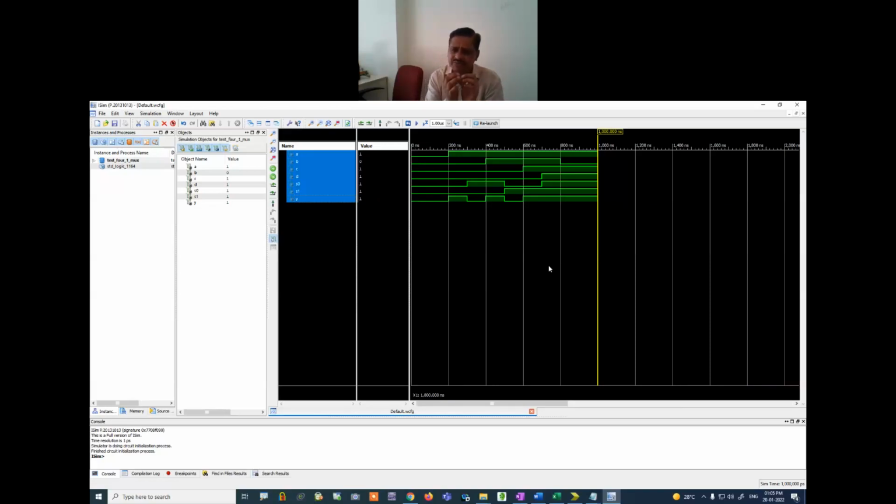Here is the same waveform. The concept we saw earlier, we call bottom-up. It means first we are designing the internal architecture and then we are designing the top module. Everything will be accommodated when we are saving the design, but when we are going from the top to bottom, in that case the top module will be created, which is an unknown module. That unknown module we have to create, and so on.